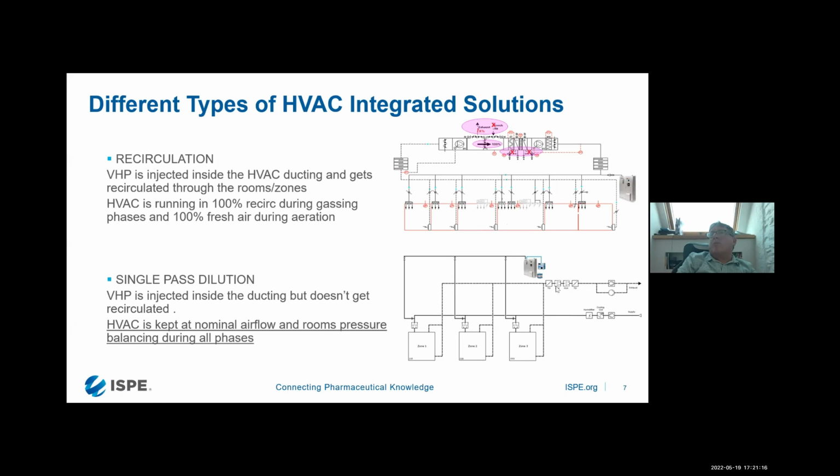But today I wanted to speak about the BSL and the great opportunity we brought to this industry where we don't need to stop the HVAC system. But in the pharma industry, we see a lot of need, and we have a lot of projects where we just connect the gas to the filter banks. We just decontaminate the filter. The advantage of this is if you have an HVAC system shared by multiple rooms, then you don't need to decontaminate all the rooms, and you just decontaminate the filter. Now, to decontaminate the filter, again,